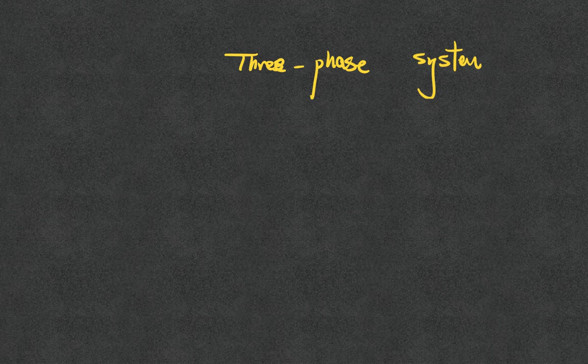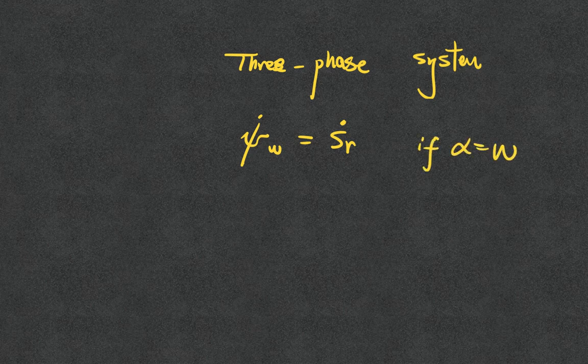So we have this interesting behavior: the change of the water phase degree of saturation is equal to this degree of saturation, but the change of the air phase is equal to the negative of the change of the water phase. You see what I mean? One's gain is one's loss. Does that make sense?